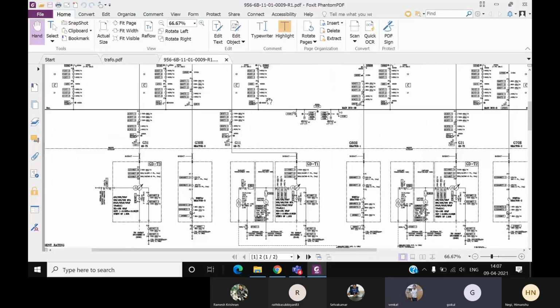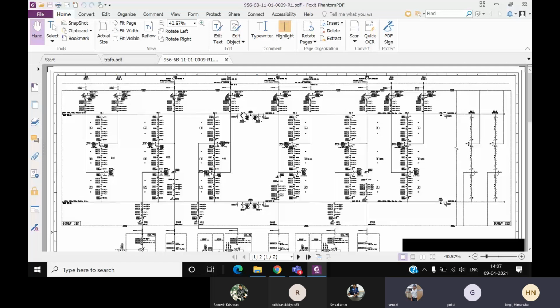So we have three transformers and three cables under OHL. If you want to talk about TOV, the first thing you have to know is what all the equipment I have in my system, and based on that you have to derive your cases. So the first thing you should know is what equipment I have: a transformer, an OHL, a cable.